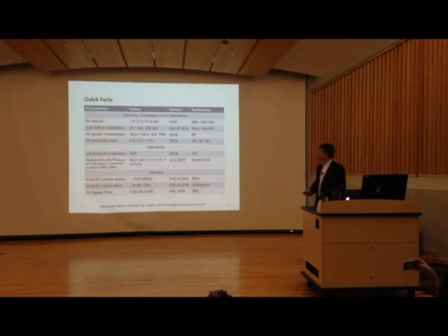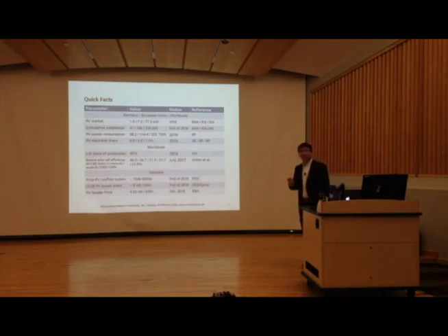Also, if you look at the worldwide share of production, most of the share is crystalline silicon. 90% of PV panels produced are silicon. Other types of technologies are not as good as silicon. They still need time to catch up because, as I said, for amorphous silicon the efficiency is a bit small, only 14%. Cadmium telluride, only one company does that. CIGS, a few companies are doing it, but if you consider silicon PV, hundreds of companies are manufacturing that type of solar cells.